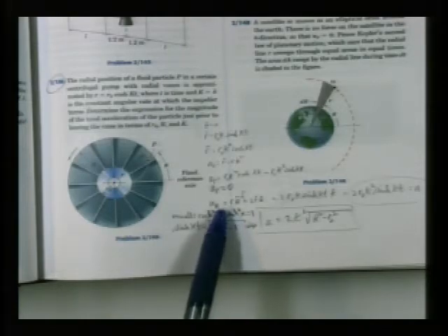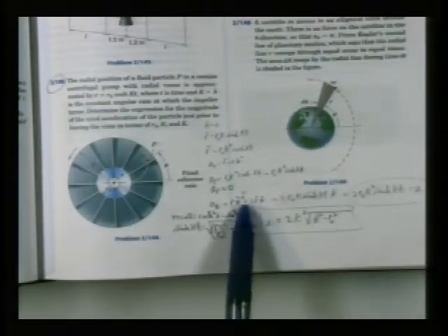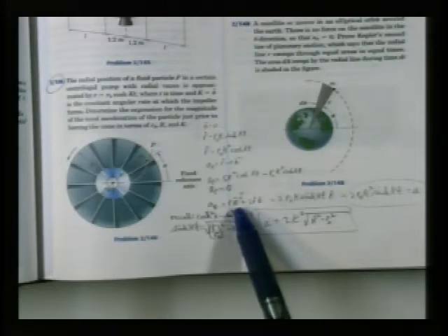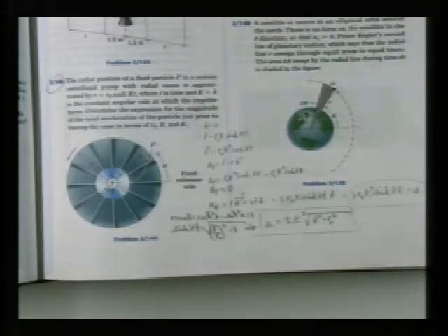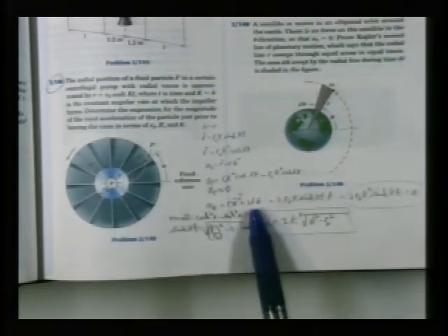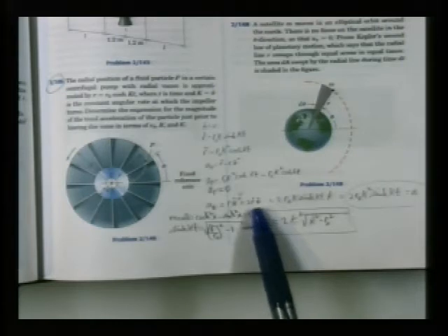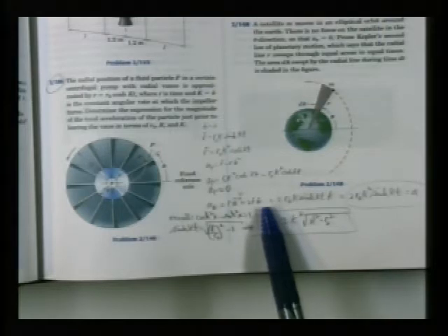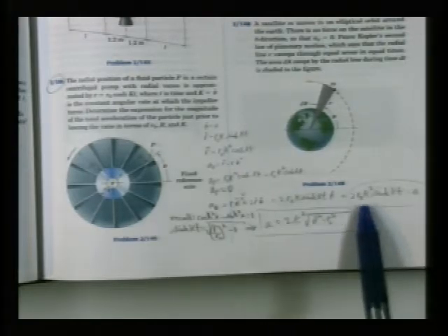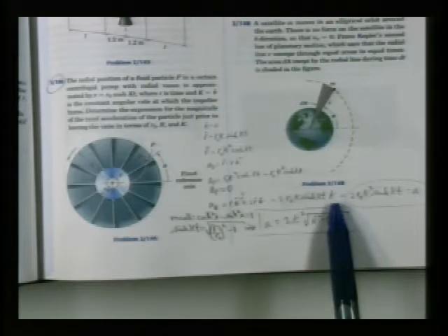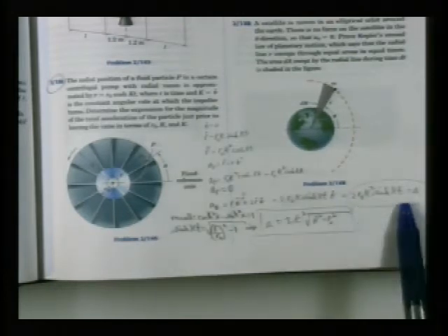Since the impeller was spinning at a constant angular speed, the theta double dot term was zero. Can you folks see that up there? Yeah, reasonable. And then the only non-zero term on the acceleration is the Coriolis effect, which happens to be 2r dot theta dot, which mathematically was this term, tidied up by combining the kappa terms into this expression.